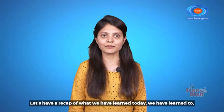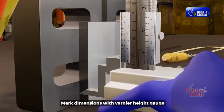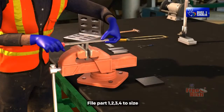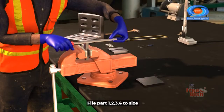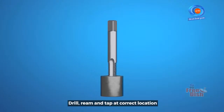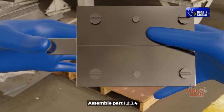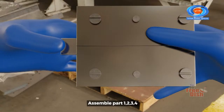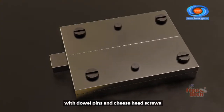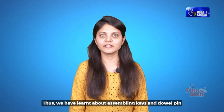Let's have a recap of what we have learned today. We have learned to mark dimensions with vernier height gauge, file part 1, 2, 3, 4 to size, drill, ream and tap at correct location, counter bore to the required depth, assemble part 1, 2, 3, 4 with dowel pins and cheese head screws. Thus, we have learnt about assembling keys and dowel pins.